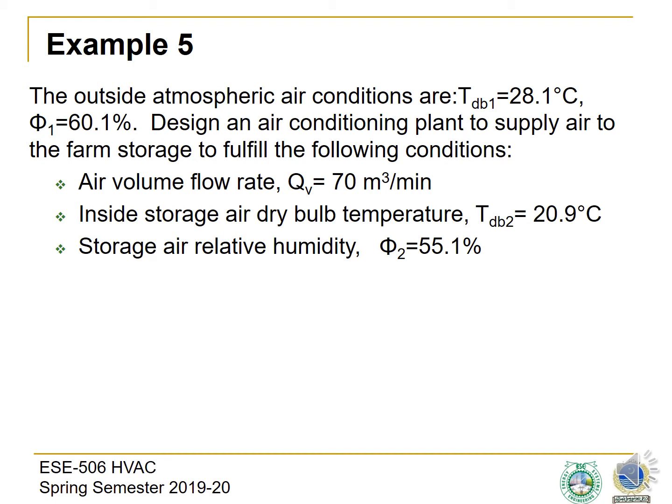Air volume flow rate will be 70 cubic meters per minute. Inside storage air dry bulb temperature is 20.9 degrees Celsius and storage air relative humidity should be 55.1%.